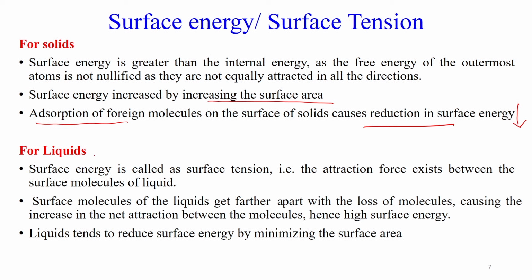And for the liquid, typically the surface energy is called surface tension. The attraction force exists between the surface molecules of the liquid. Surface molecules of the liquid get further apart with the loss of molecules, causing an increase in the net attraction between molecules, and in this case they will have high surface energy. This can be tuned by some external means like change in the temperature or change in the pressure, and liquids tend to reduce the surface energy by minimizing the surface area.